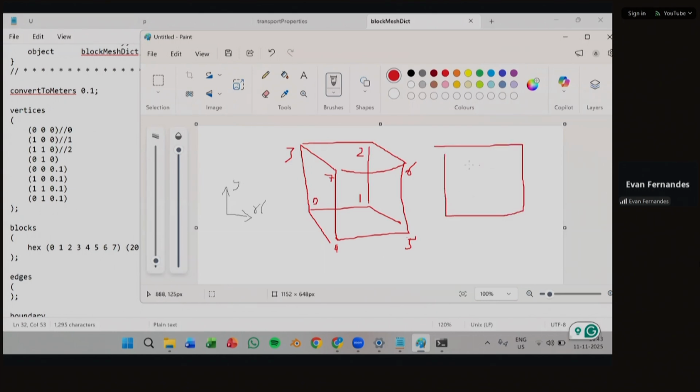If you were to make a mesh closer to the wall, now with this particular simple grading, all my mesh went towards the left, right? So here we had fine mesh, and then here it became coarse. But with multi-grading, you can split this entire line, or your entire X direction, into multiple parts. So I can say that in this corner, I want fine mesh. In this corner also, I want fine mesh. And as you move towards the center, I want it to be coarse. So multi-grading gives you that ability to manipulate that whole block as per how you want it.